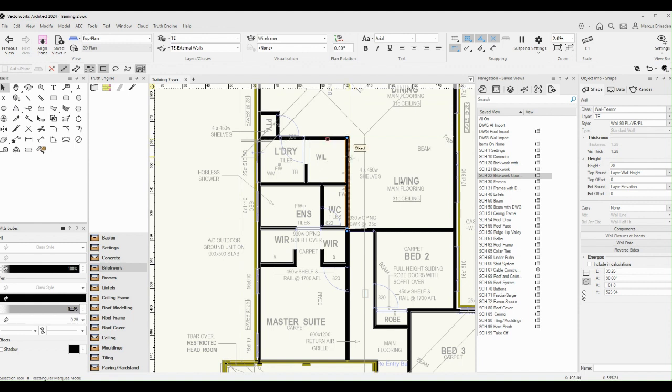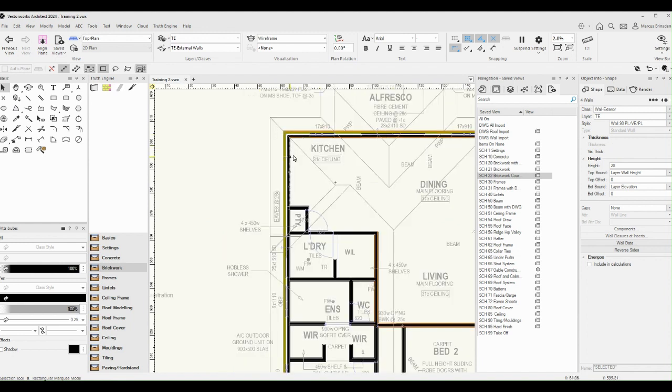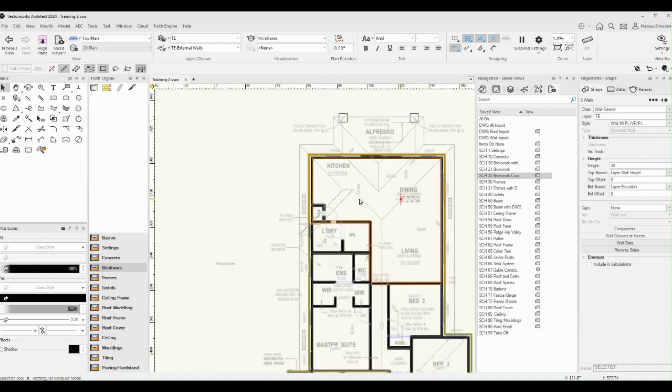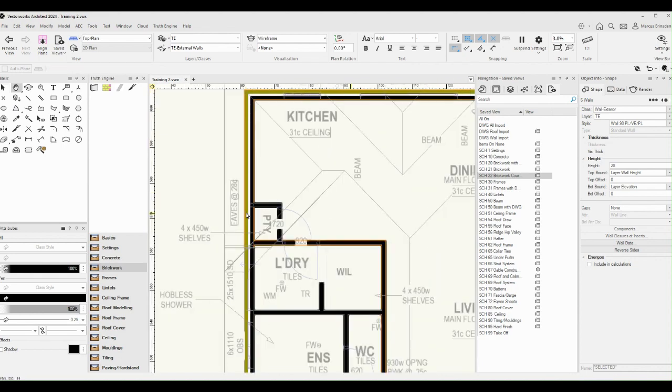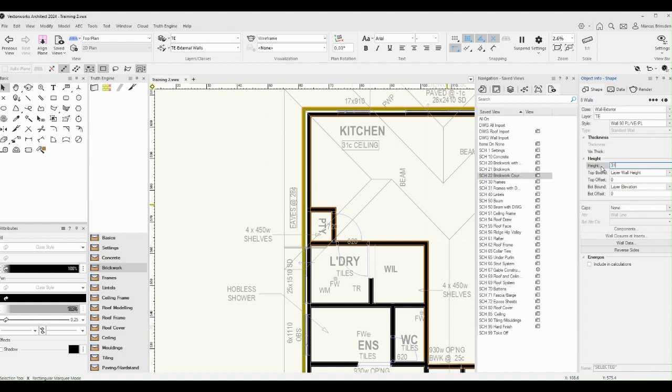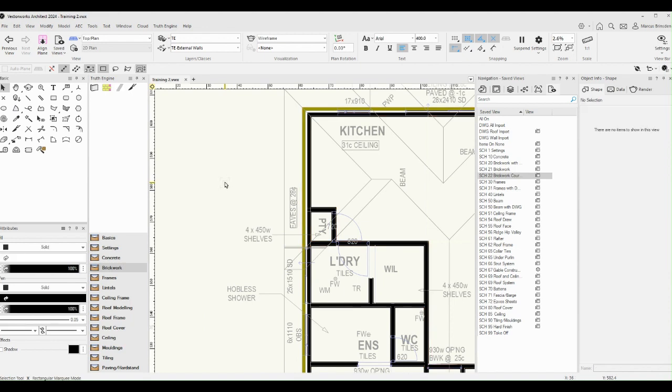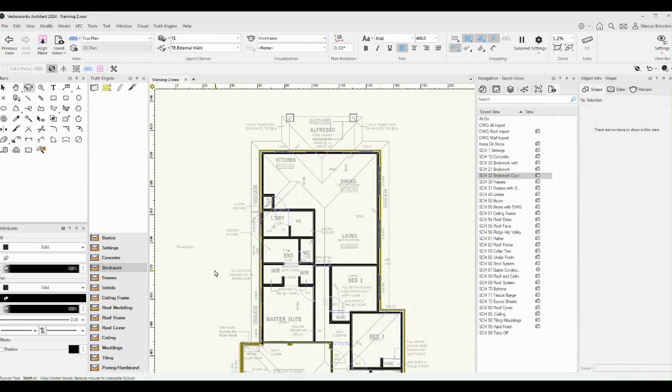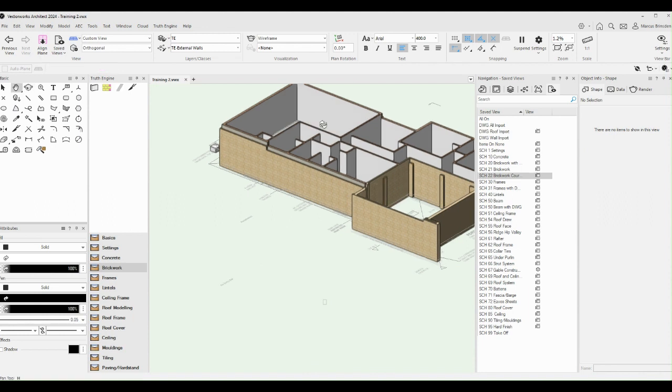Okay, so now I can select that wall, that wall, that wall, this wall, and this wall, and this wall, and that's basically created an envelope of your 31 course ceiling, and we'll also grab these walls here. They need to go up 31 courses as well. And just type in 31. So look at that in 3D. Perfect.